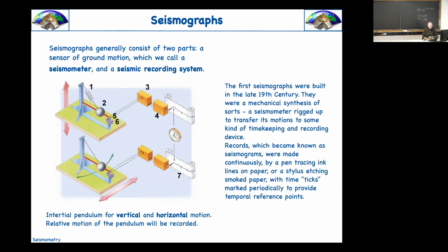Now, just recalling in one minute some theory about waves, we know that P waves are longitudinal, so they can have a component in all directions. S waves are transverse, so according to your orientation, the wave field will look different. But surface waves, like Rayleigh waves and Love waves: Rayleigh waves are P and SV, radial and vertical, and Love is just transverse.